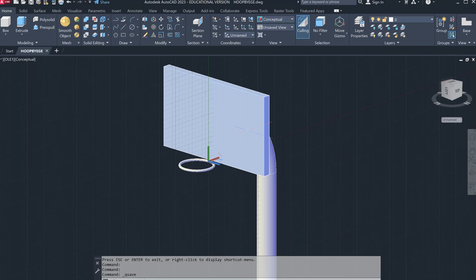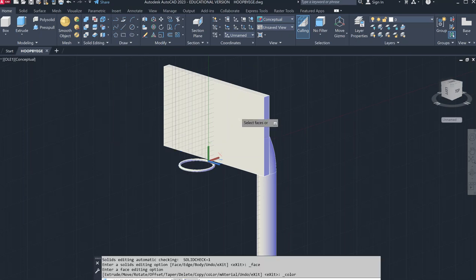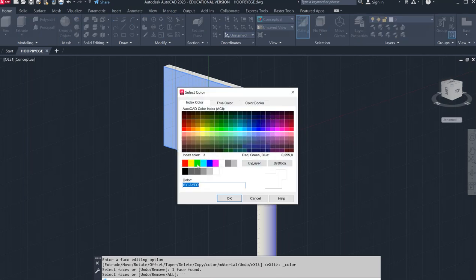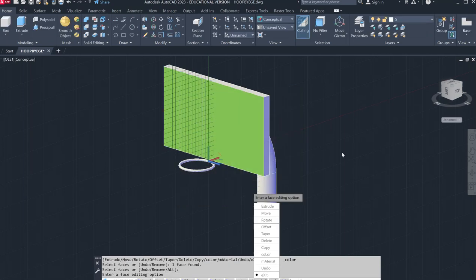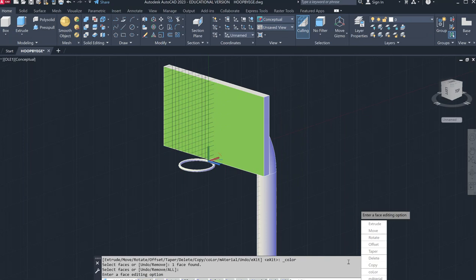And you can select the surfaces and then change the colors as well. For that purpose, we have the solid model color surface commands. Color the surface. You choose the surface, Enter. It gives you a bunch of colors, and probably green or darker green is a better color. Okay, and then you can turn off the grid mark.